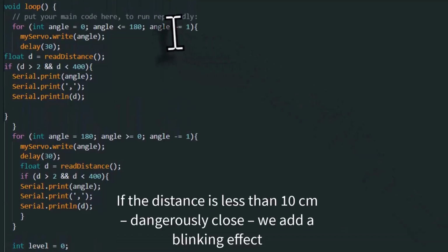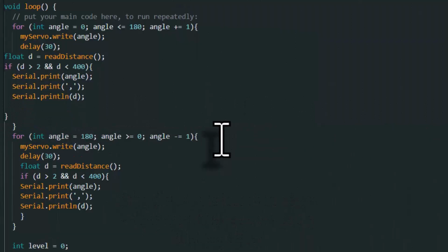Already with this line, we say that each time the loop is running, we increase the position by 1. So it will increase by 1, but here we said we will decrease it by -1, but I want to decrease it more than 1. Why? Because it will concentrate on the object. So if the object comes closer to the sensor, less than 10 centimeters, the servo will move more slowly. It will concentrate exactly on that object until the object goes away and gets more than 10 centimeters distance from the sensor. Then after that, the servo will go again to the normal speed.